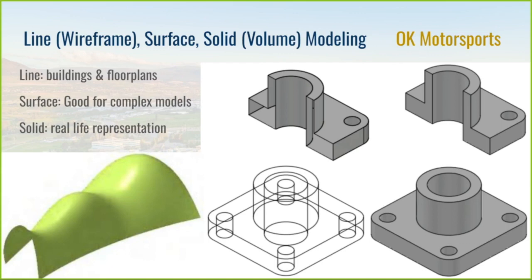So wireframes are like that, very, very simple, used in building and construction stuff a lot, floor plans. So if you're in civil, you're going to be doing a lot of that in AutoCAD or Inventor Studio. What wireframes are good for people that aren't in civil or mechanicals, which I'm guessing a majority of you usually are, is that it allows you to kind of have X-ray vision through your part. So you can say, oh, from looking at these ones, I can only make 3 bolt holes on that base plate, but when I turn the wireframe on, I know there's a 4th one behind that center tube thing.